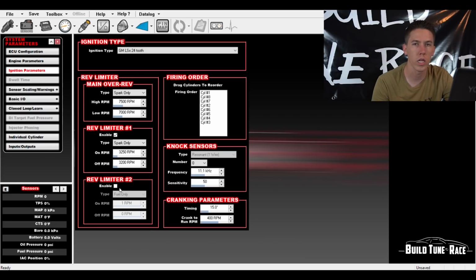So we use the 3-step. He comes up on the foot brake, it's a lower rev limit, and then when he grabs the trans brake, it moves it to the rev limit 1, which would then be the 2-step. So cranking parameters, those are already preset, real simple there.